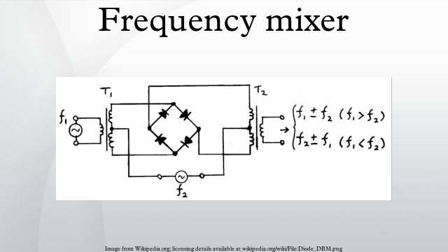In the frequency domain, the switching mixer operation leads to the usual sum and difference frequencies, but also to further terms, for example ±3 f_LO, ±5 f_LO, etc. The advantage of a switching mixer is that it can achieve, with the same effort, a lower noise figure and larger conversion gain. This comes because the switching diodes or transistors act either like a low resistor or large resistor, and in both cases only minimum noise is added. From the circuit perspective, many multiplying mixers can be used as switching mixers, just by increasing the LO amplitude. So RF engineers simply talk about mixers, and mean switching mixers.